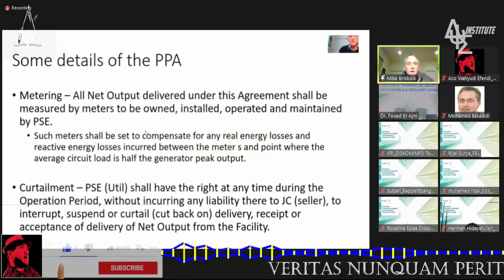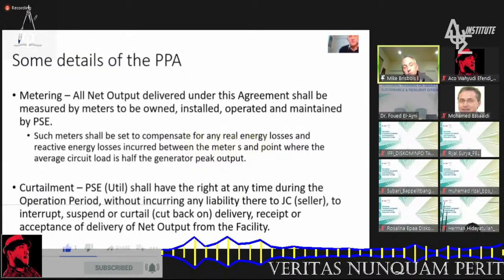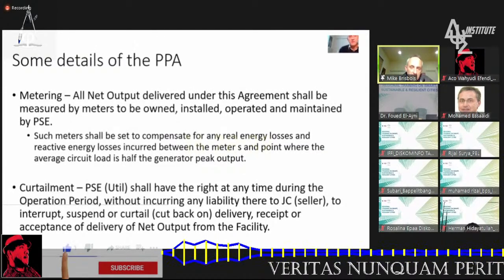is. Some details, metering. So net metering: we have to put a net meter on your facility where you can actually turn the meter backwards. It's actually a separate meter. You're sending power back to the utility grid, where the grid is actually purchasing it. You're getting units, and that's all calculated. And then when do they cut you off? How much power can you give back? It's not infinite. There are certain amounts of power. It's all metered by using the advanced metering system that the utility provides for us. So those are all things that we need to take into consideration.